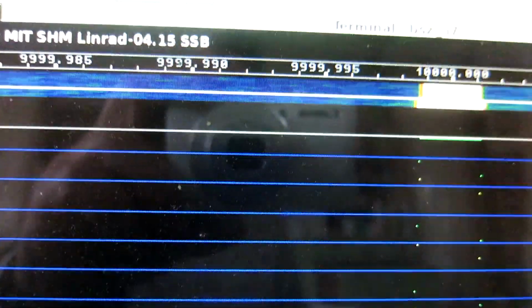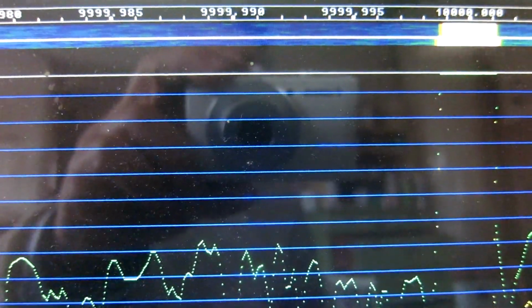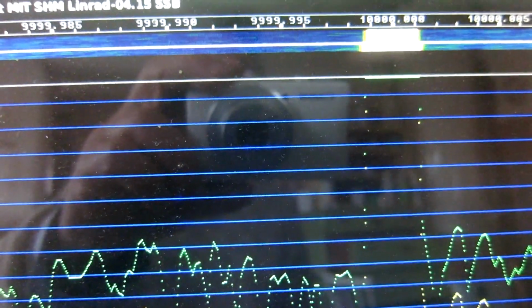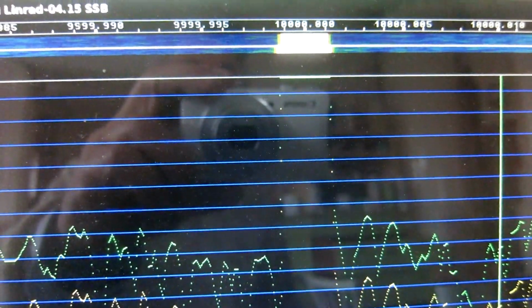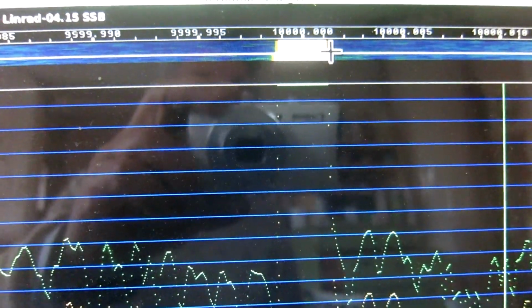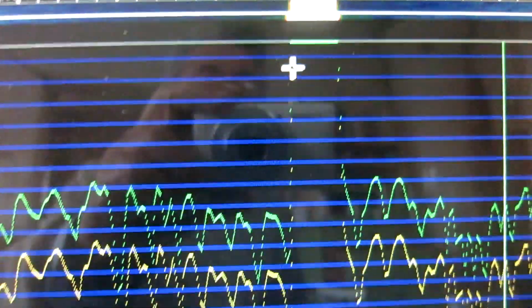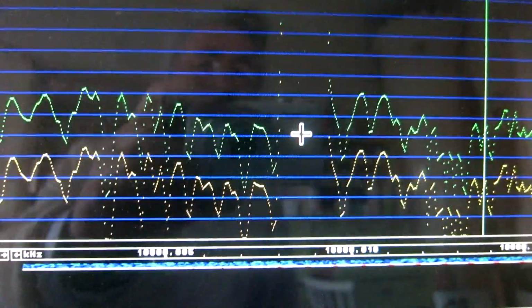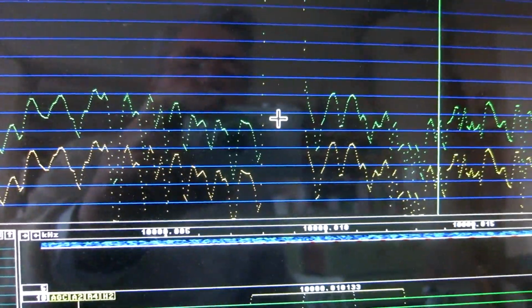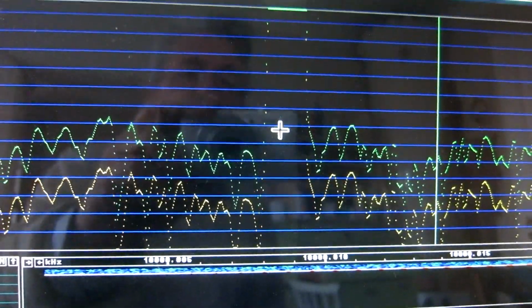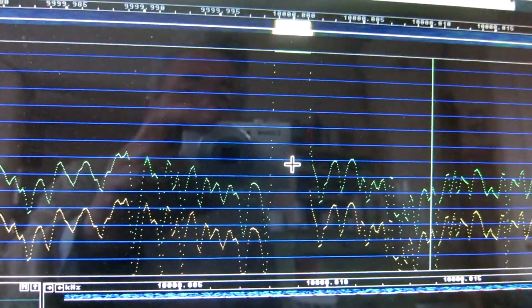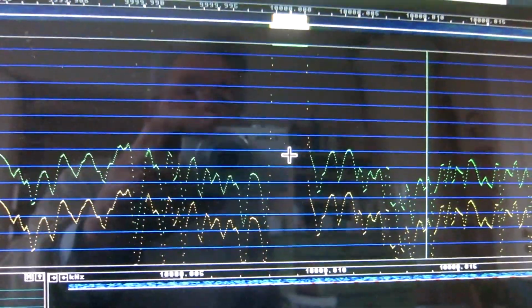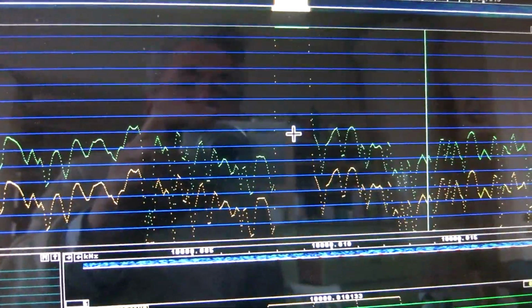I don't know. And you can see also on the waterfall that the white line is where I switched the power, and you can see the width of the signal is slightly smaller. This is the signal that comes through the interferometer, so it is suppressed, balanced to ideally 0, but of course there is some level of the carrier because balance is not perfect.